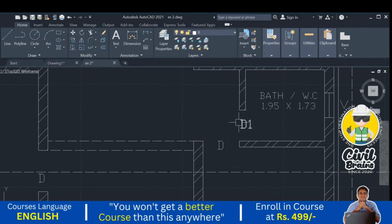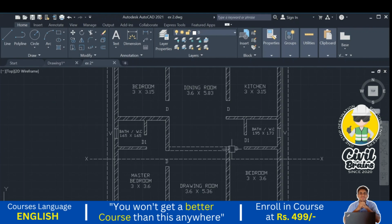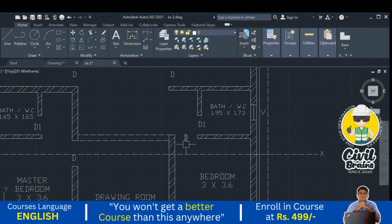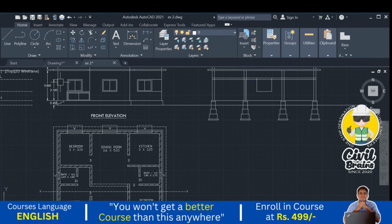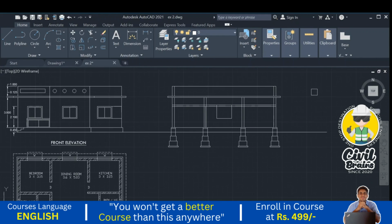Because of this, see here the wall is ending exactly here only. If we make it 1 meter again, then it will come here. So because of that only we did a 0.9 meter door. There is no issue. 0.9 meter and 1 meter doors we are providing for the bedrooms. So how much is the door width? 0.9 meters. So we need to show the door here. I go to the offset command, provide the door width 0.9, press enter.